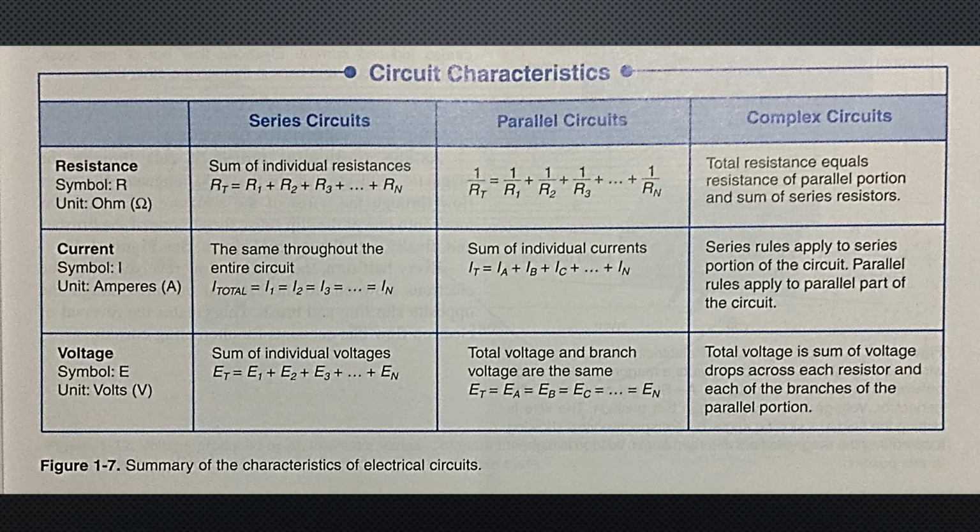So if you notice, the current total and the voltage total swap in each of the circuit types. Voltages are additive for series and they're equal for parallel.